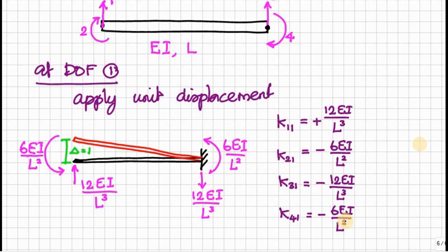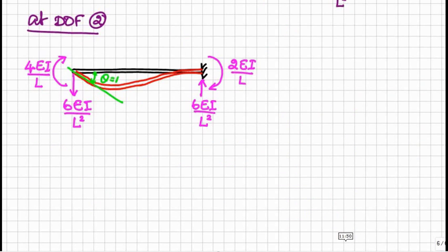Now we have to apply unit rotation at degree of freedom 2, because degree of freedom 2 is a rotational unit. Therefore, we have to apply a unit rotation at degree of freedom 2. Then we have to measure all the forces. So this is the scenario.